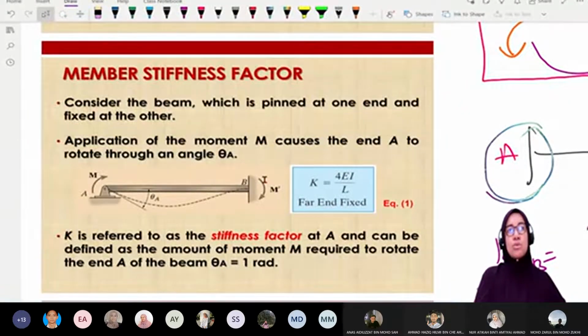So normally when you learn structure analysis, everything has a reason. Why I need to calculate reaction, why I need to calculate internal forces, why I need to calculate displacement. So you have to have the answer to all these questions. For example, how do I calculate displacement? I calculate using the unit load method or principle of virtual work. So how to do that?